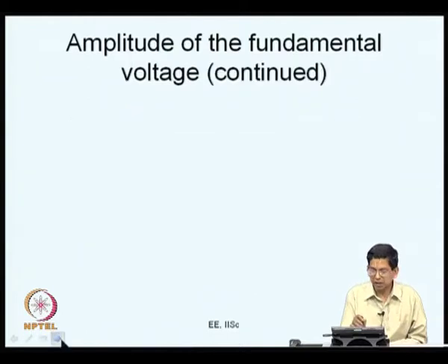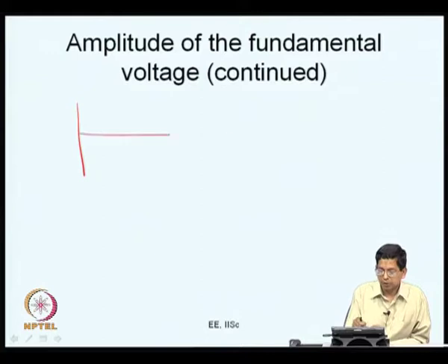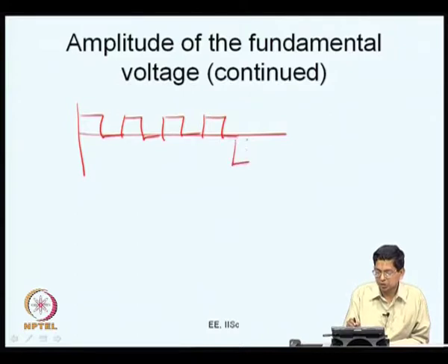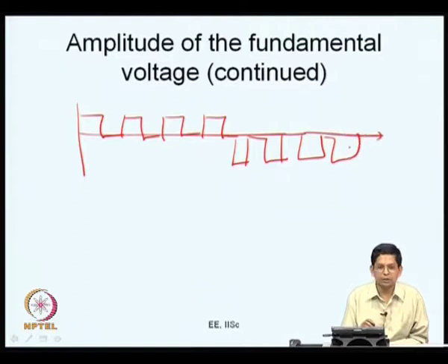So, this is another part, how you want to control the amplitude of the fundamental voltage. There are various ways in which you can do that. There I had introduced a single notch, whereas you can also introduce several notches like this. This is an example very similar to the previous examples that we saw. You can introduce a few notches or more notches, and more notches means the device inside the inverter switches more number of times. So, that places an upper limit.